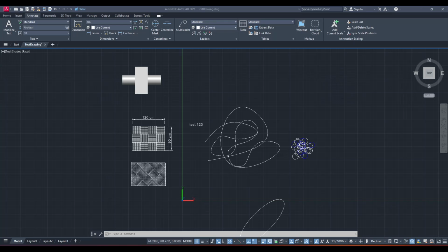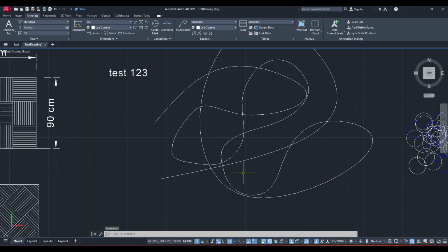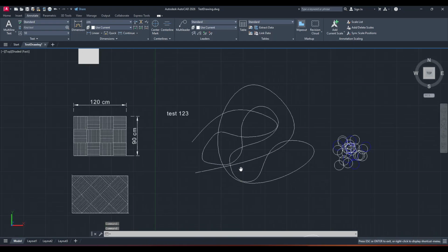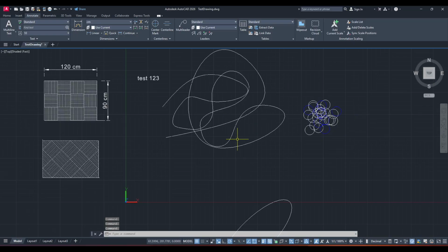In today's video, I'm going to teach you how to remove grid or turn off grid display in AutoCAD. If the dots or lines filling your workspace are getting in the way, this quick guide will show you the fastest ways to hide them so you can focus on your geometry without distractions. The grid is just a visual reference. It doesn't affect your drawing or accuracy, so turning it off is completely safe and reversible.